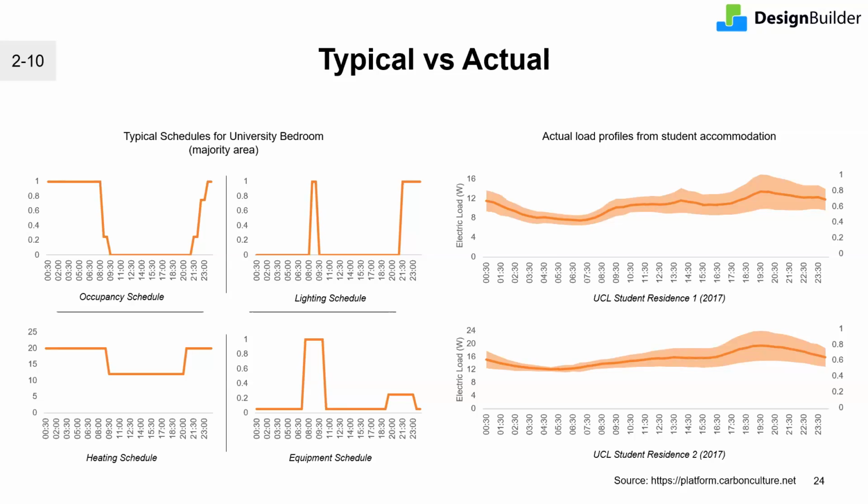A structured discussion with the client is therefore useful in these cases, typically to understand occupancy patterns, operating hours, along with the way the building would be managed eventually. And ideally, this should be backed up by data rather than estimates. So for our model, let's do the more realistic customizations for the occupancy inputs.